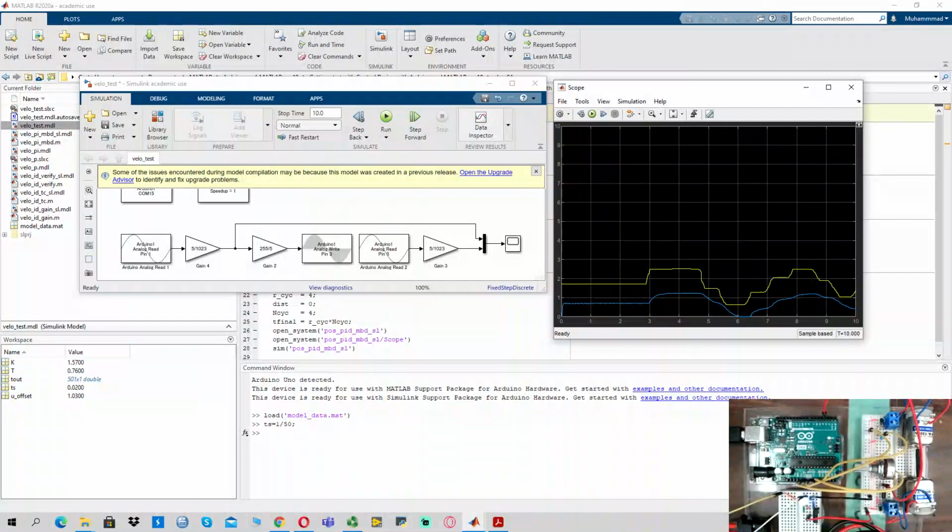next we will test the basic proportional control. Basic proportional control is a simple controller where we have an input target value, and then we have a deviation from the output that we are measuring with the tachometer sensor, which is an analog sensor. We have a controller, the proportional control, and the control object is your DC motor.